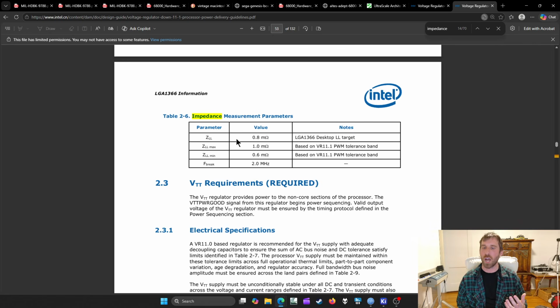So there may be some kind of a reference document for a motherboard. But it's probably under an NDA. So we won't get to see that. So for AMD, no dice. Forget about it. So Intel's a lot more open when it comes to this stuff. So they don't even tell you what capacitors to use. They just say, here's your impedance target, hit it. So question is, how do you do it at the level these guys are working at?